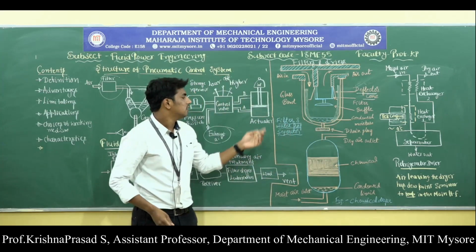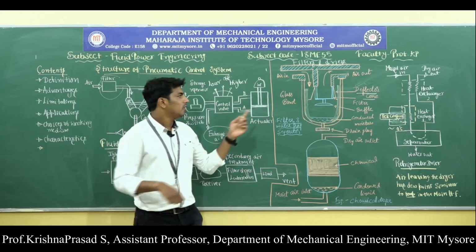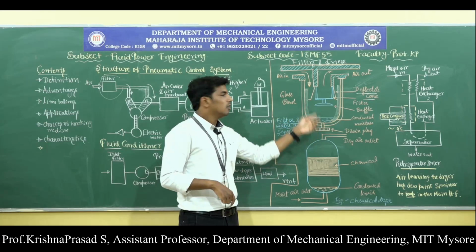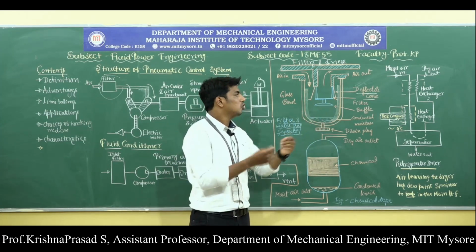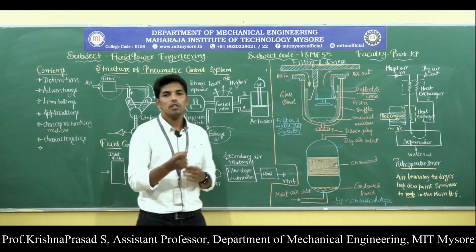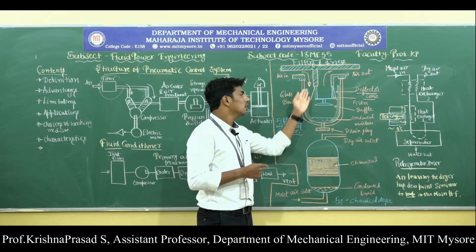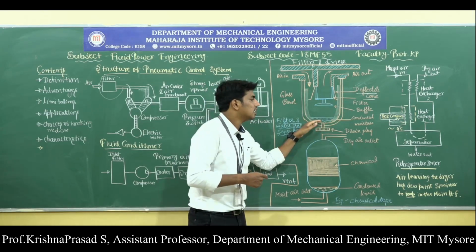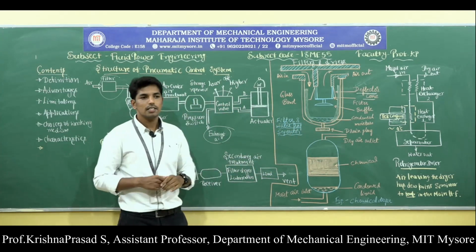So this is called the filter and water trap separator unit. I repeat, here air passes through the air inlet, then it undergoes a sudden change in direction of flow. After that, it is going to swirl because of the deflector cone. Because of the swirl and the change in direction of flow, whatever heavier particles are present will be flung out against the separator wall, and then collected at the bottom. So this is called the filter and water trap separator.